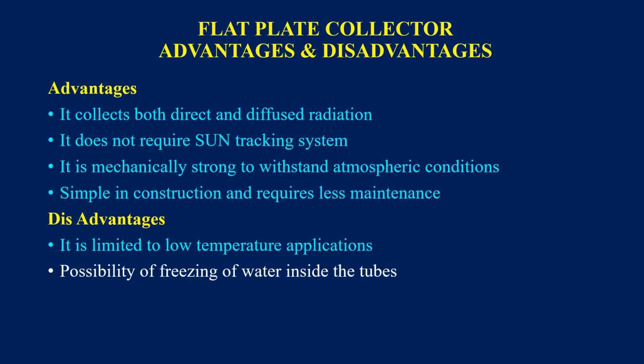This can be avoided by adding anti-freezing agents like ethylene glycol, but this addition reduces the heat transfer capability of water. Another solution is that after using the device, we can drain the water from the tubes and then refill it again when we have to use it.